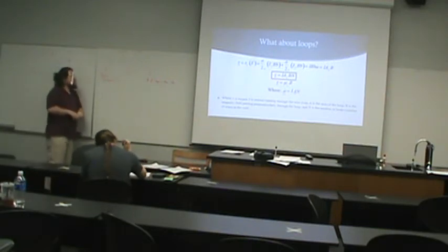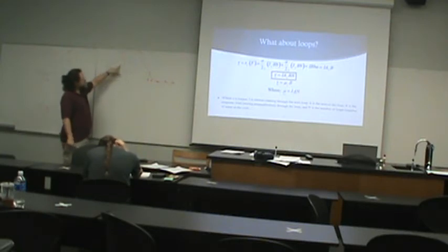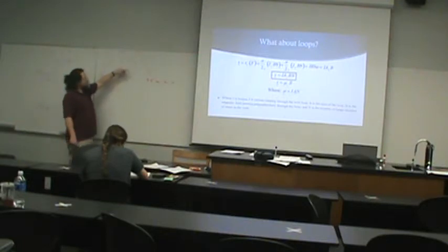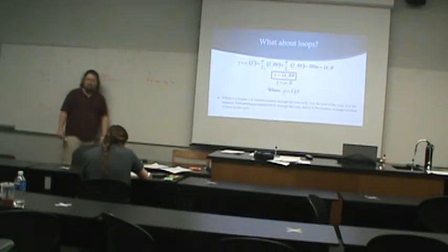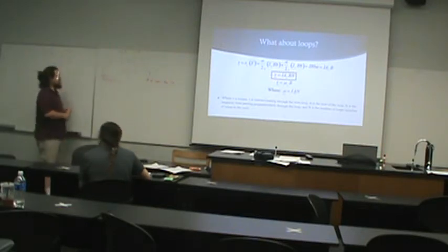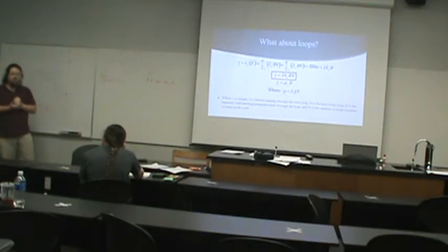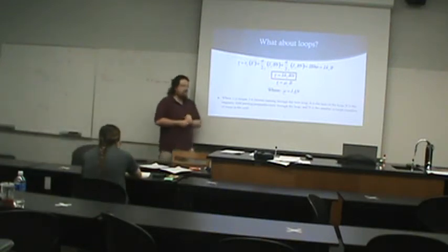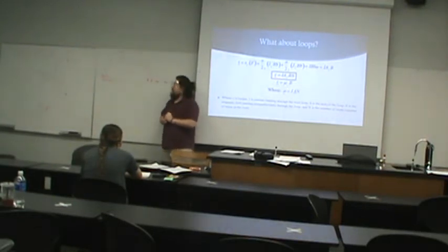Similarly, if you want to increase the power, you can increase the current. You could increase the size of the loop, although depending on how big your machine is allowed to be, that's kind of a limiting factor. But you could if you wanted a more powerful one, and you could also crank up the magnetism. All of those things, when increased, make the motor more powerful. I think the most cost-effective and space-efficient way of increasing the torque, though, is just the number of loops.